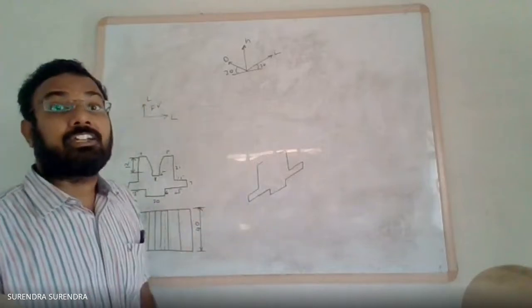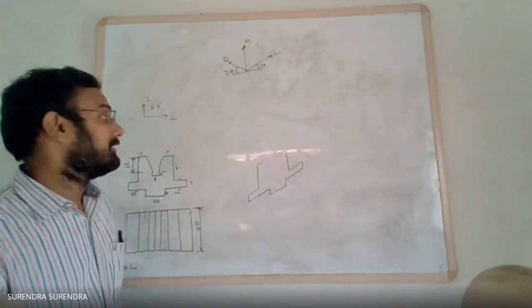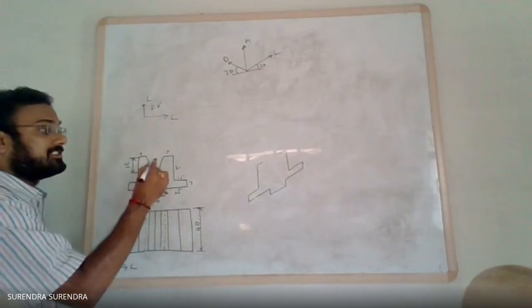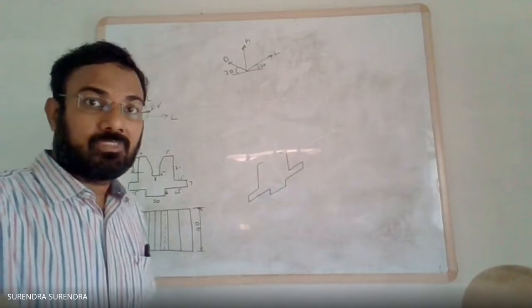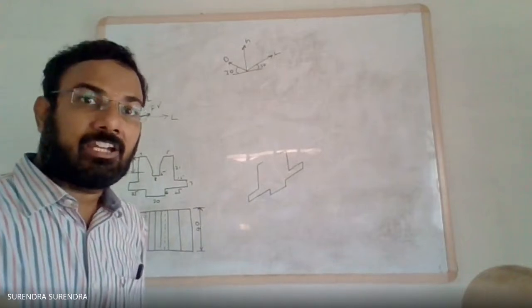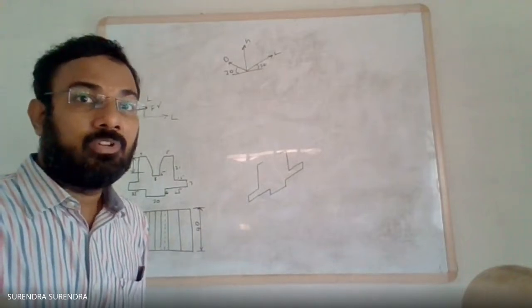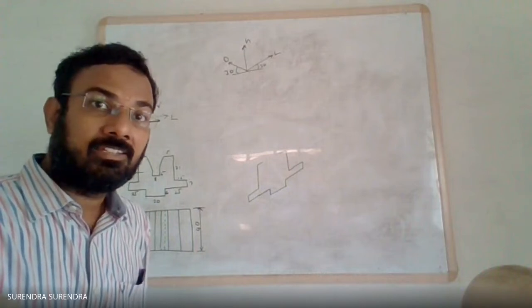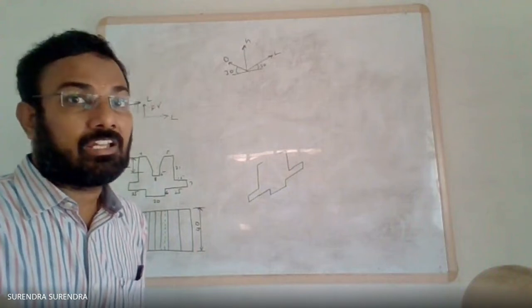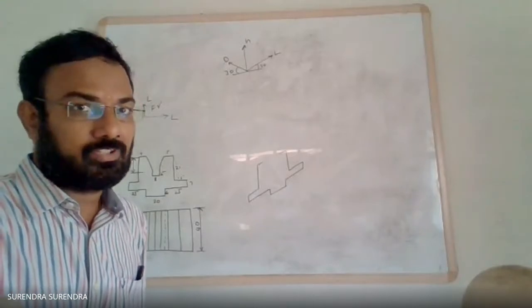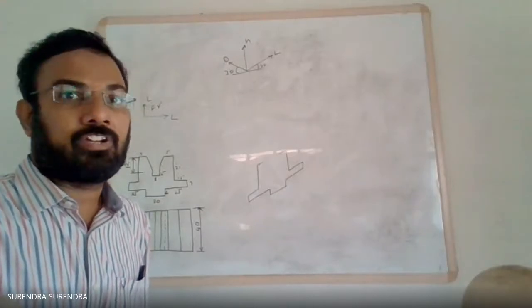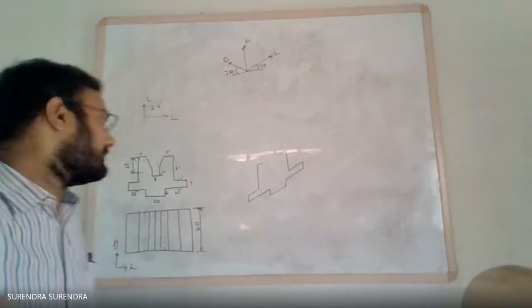Along 30 degrees inclination. Now, for getting these inclined lines, we will never prefer drawing directly. Last class we saw, while drawing a pentagon, when there was an inclined line we inscribed a square or a rectangle and transferred those distances. Here also, there is no need of inscribing, but we will first get those endpoints.